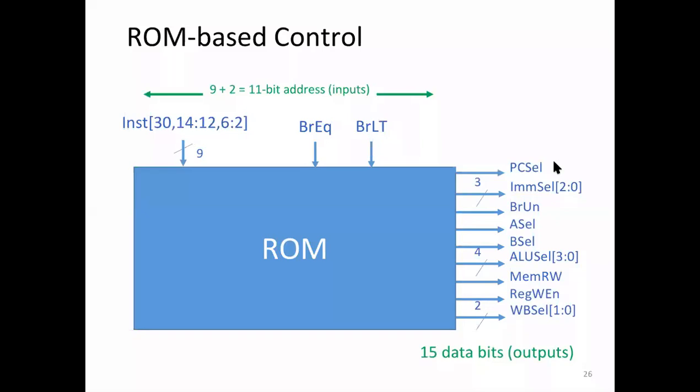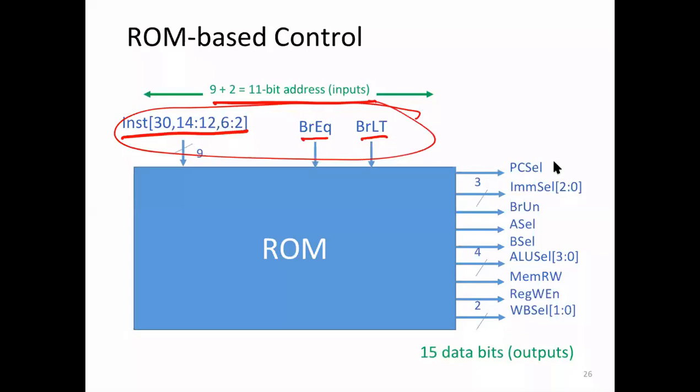The first method is microprogram. Note that this word, microprogramming, is very often used in interviews. It's nothing but generation of control signals using the memory method, or basically we treat this as a small program. So what we do here is that these are the 11-bit inputs. We have seen 9 bits are coming from the instruction and these 2 bits. And then we read a location corresponding to that instruction, and this output is generated. So this kind of design you can easily do, right?